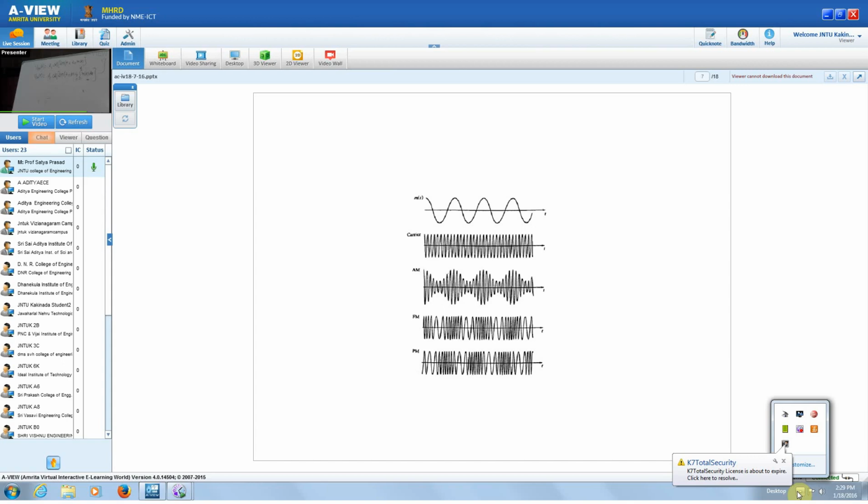If you look into these three, AM, FM and PM, in the case of AM, as the modulated output crosses 0, the spacing between zeros is the same, because your carrier frequency is not changing. The same carrier frequency is there, therefore the zero crossings remain the same. The only thing is, whatever the variation in the baseband signal is reflected in the envelope of your modulated signal.